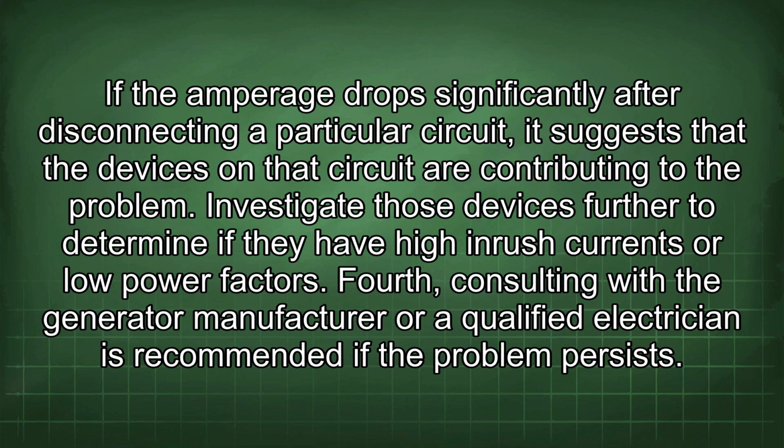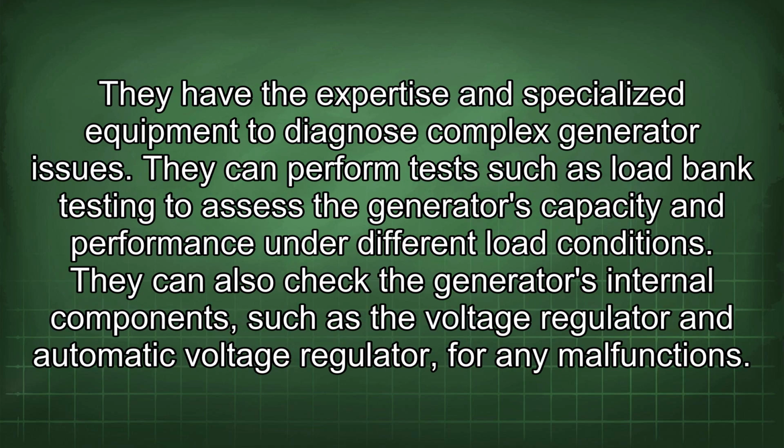Fourth, consulting with the generator manufacturer or a qualified electrician is recommended if the problem persists. They have the expertise and specialized equipment to diagnose complex generator issues. They can perform tests such as load bank testing to assess the generator's capacity and performance under different load conditions. They can also check the generator's internal components, such as the voltage regulator and automatic voltage regulator, for any malfunctions.